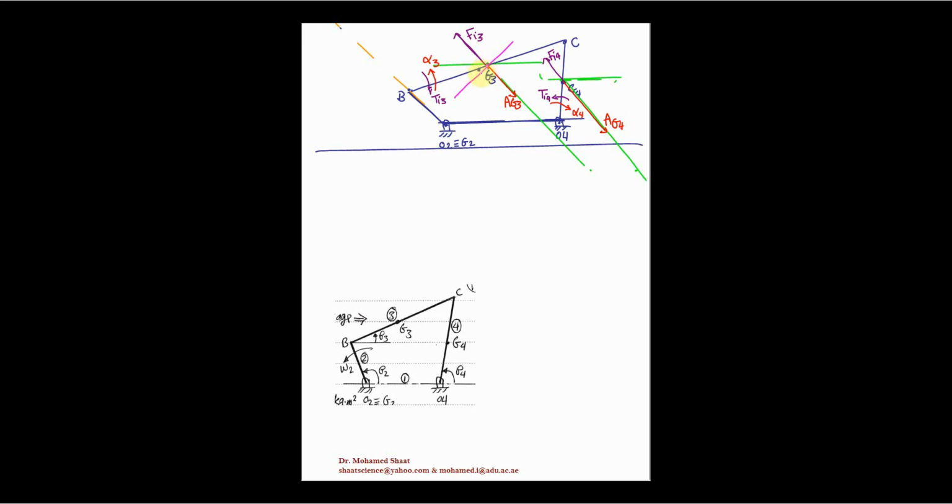So we measure 4.4 and mark a point. Then from this small point, you're just gonna draw another very light line in this way. This line should give us the direction of the new force, parallel to the original inertia force, that is going to replace both of the forces. So we're gonna draw a line from this point in this way. This is gonna give us the new force, the new Fi3. This is the new inertia force.